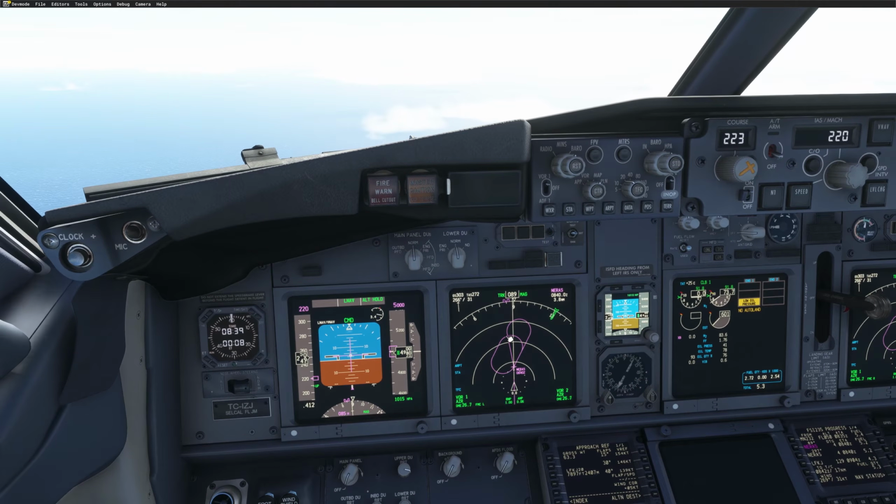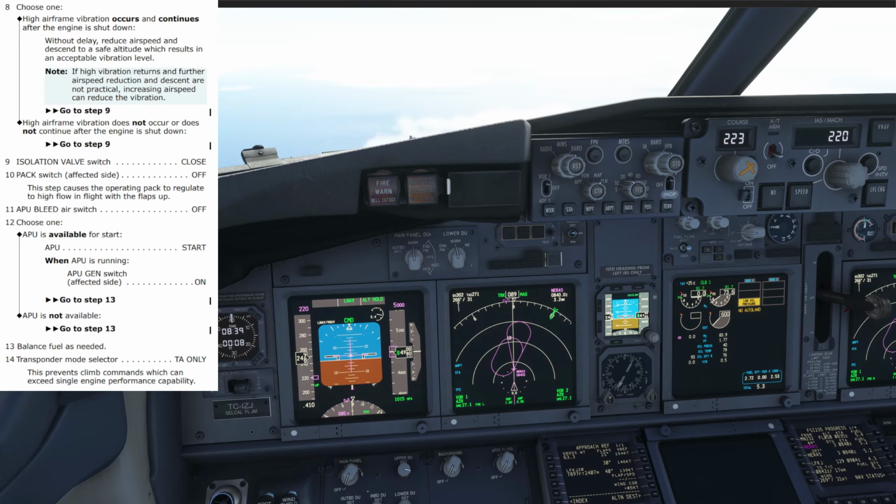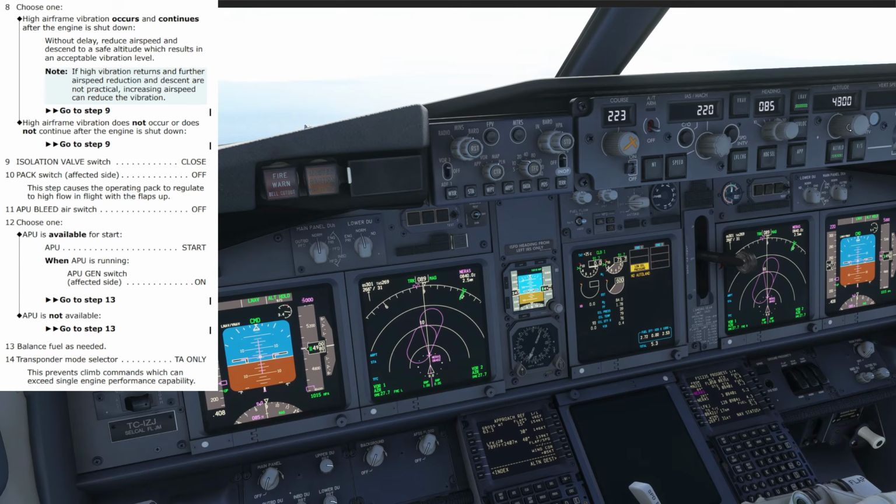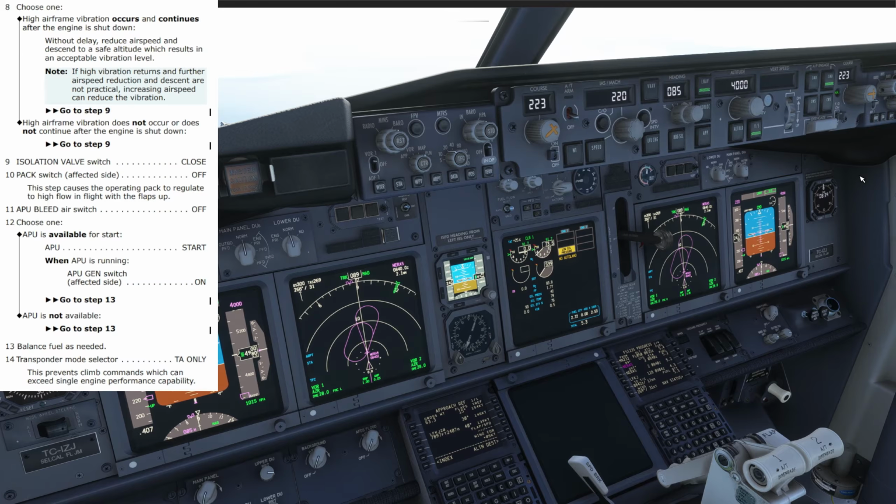So for that we have a QRH, so we'll bring the QRH for engine fire, severe damage or separation. And that's the rest. FSiPanel 235. Descend 4,000 feet. Report ready for the approach. Fire brigade has been advised. Roger, descend 4,000 feet and we'll report ready for the approach, FSiPanel 235.